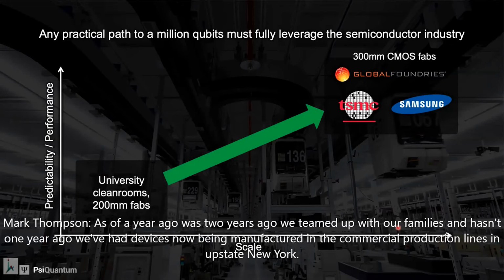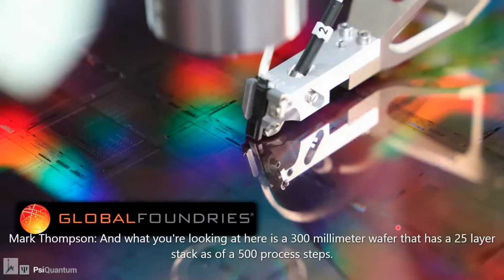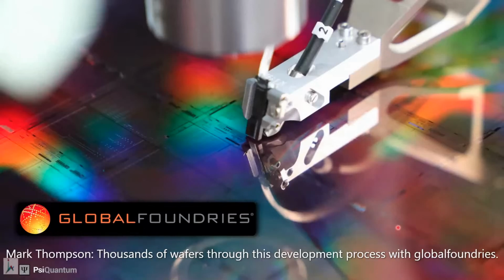And as of 2 years ago, we teamed up with GlobalFoundries, and as of 1 year ago, we've had devices now being manufactured in the commercial production lines in upstate New York. And what you're looking at here is a 300mm wafer that has a 25-layer stack. It has over 500 process steps. We've put 6 processing tools into the production line at GlobalFoundries to enable this technology. And on that wafer are thousands of single photon sources and thousands of single photon detectors. And we've now processed thousands of wafers through this development process with GlobalFoundries.